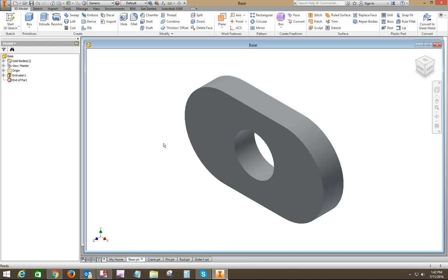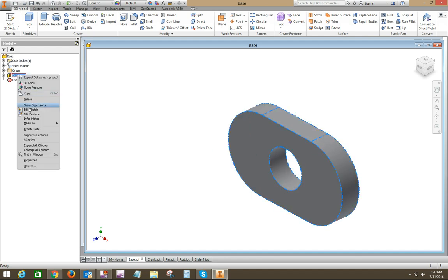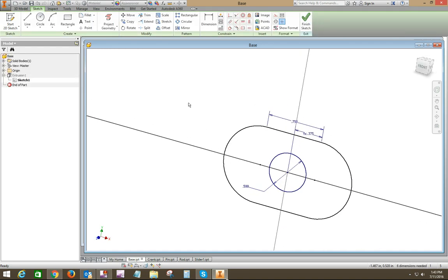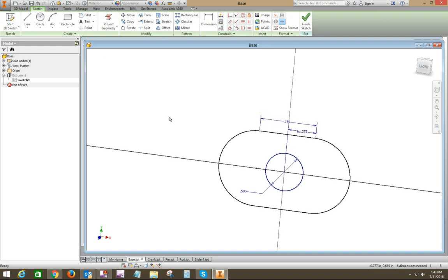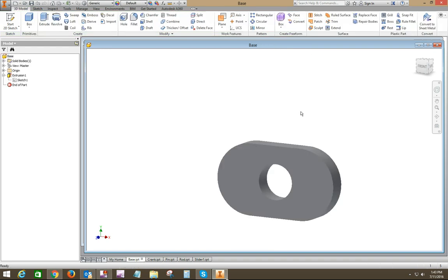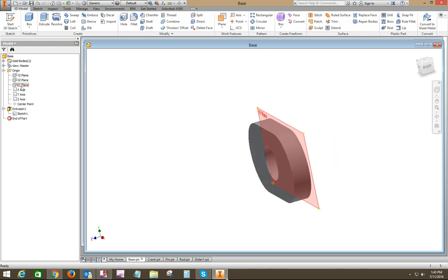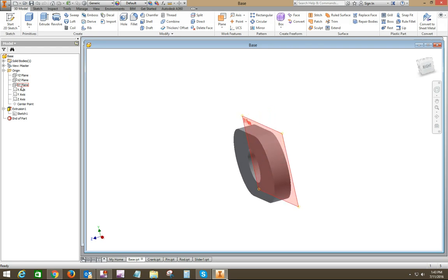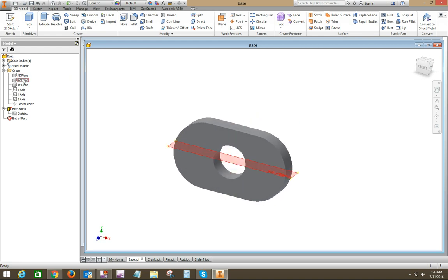Okay, so let's look at these. Here's the part we call the base. These parts are really pretty simple. The sketch on this one, if you notice, is symmetrical about my origin. This dimension is set to be half of this dimension. That's the type of dimensioning system we're using in the way a lot of these parts are created. Most of these things are centered on the different planes. On the back it's not a big deal because of the way they mate, but because of the way this project goes together, it's easier to create the parts centered about the X and the Y axes.